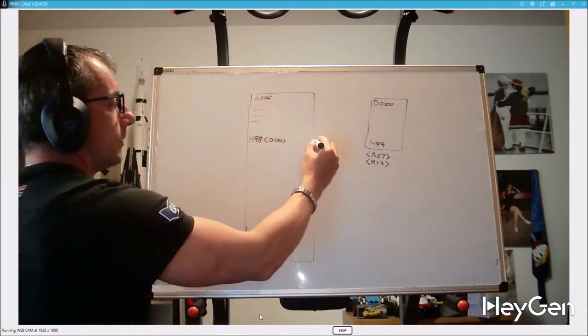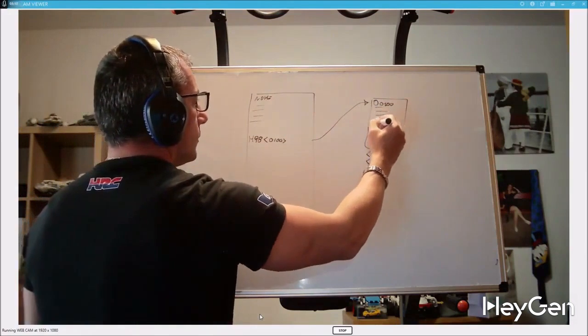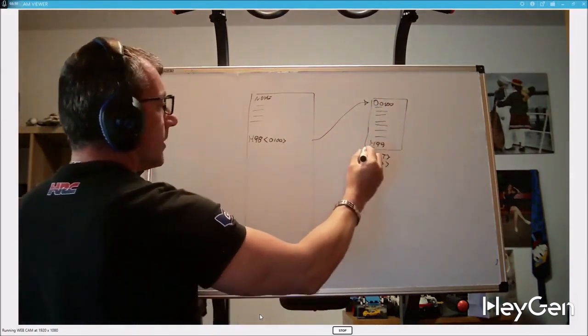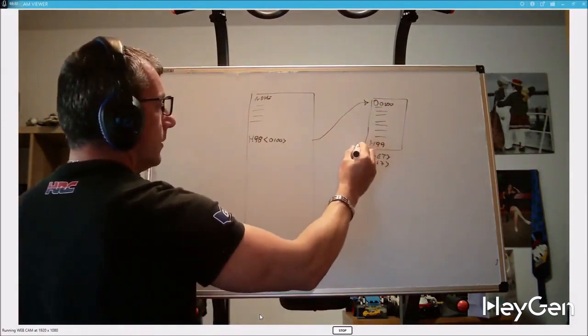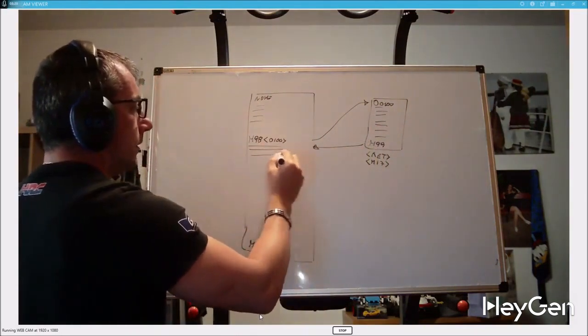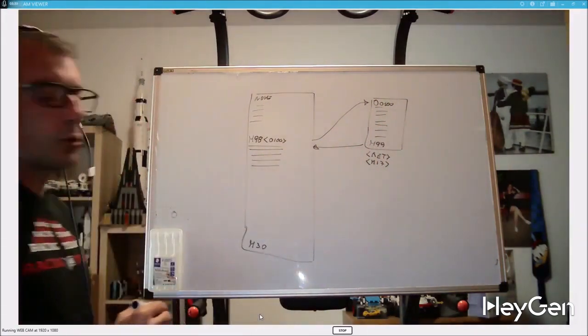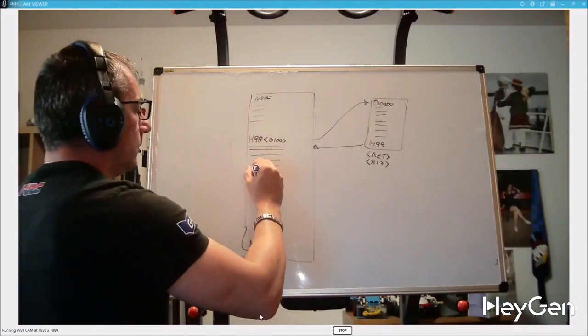Also, this subprogram can be called multiple times within the main program. Additionally, we can call 1,000 subprograms as needed. In fact, a main program can be made up entirely of subprograms. Why use this? Reasons include it can be used to repeat a groove multiple times with slight advancement. It can also help manage a family of parts.